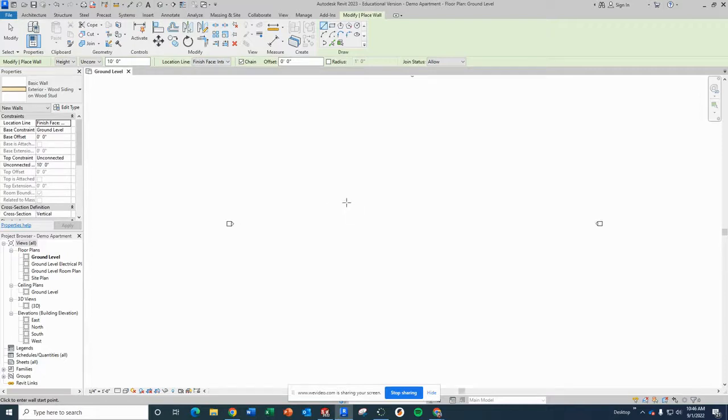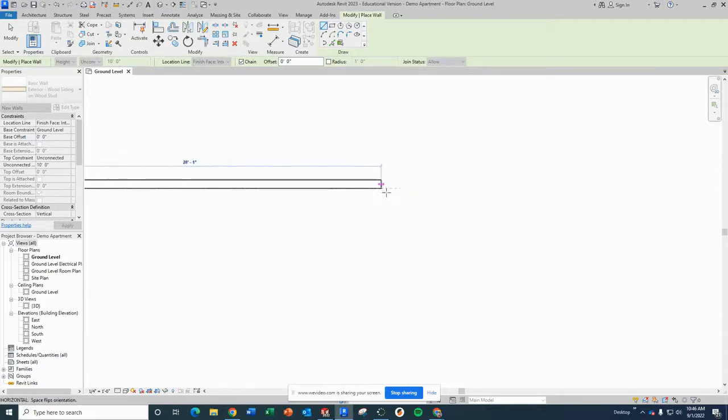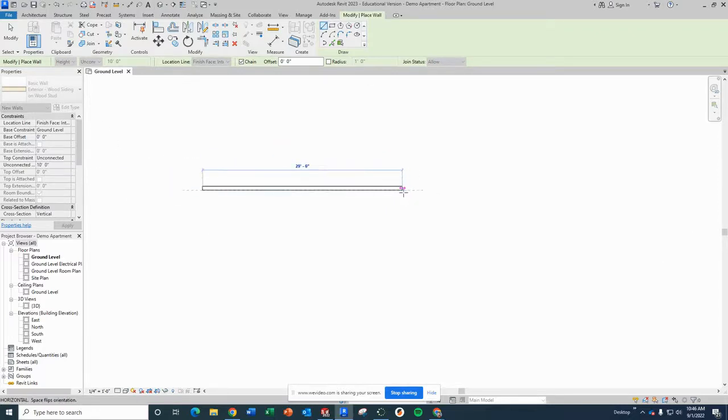What that means is as I draw a wall, which I'm just going to click out here and start to draw, as you can see, I am drawing a line and it's basically creating that three-dimensional wall that's 10 feet tall, with my line being the inside or the interior wall, the drywall side of the wall, if you want to think of it that way. So you usually want to draw your walls in a clockwise fashion as you go around a shape. That should keep the exterior surface on the outside. If they're accidentally backwards, there is a way to reverse them.